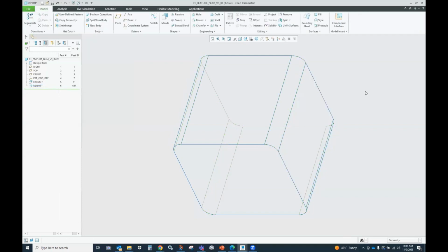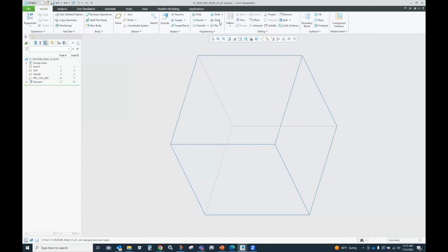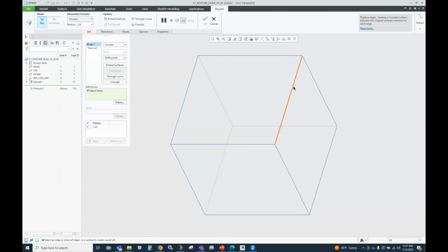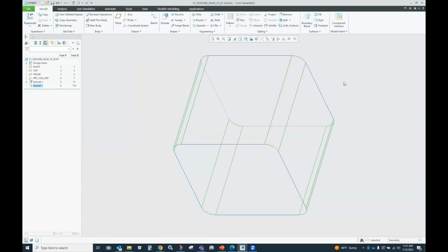Middle mouse button is finishing the round. So I can actually get very fast at creating these rounds, right? So I'm going to do it one more time, create the round, put my cursor there, tap right, pick middle, and all those rounds get created. Not only is it faster, but it's more robust. So the moral here is that control key is not always your friend. Sometimes you can't get around it, but look for other options that are more robust, okay?